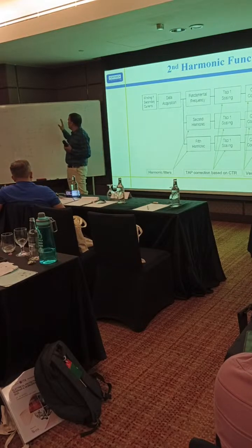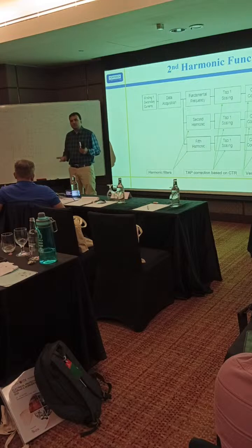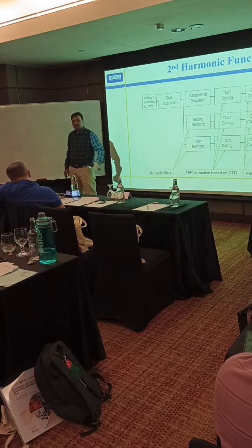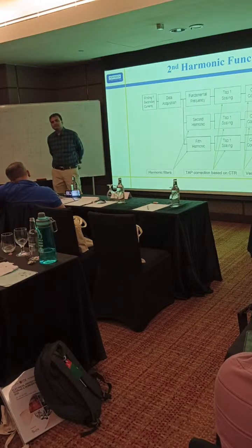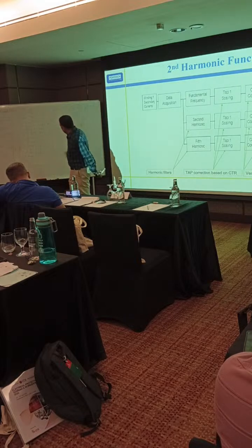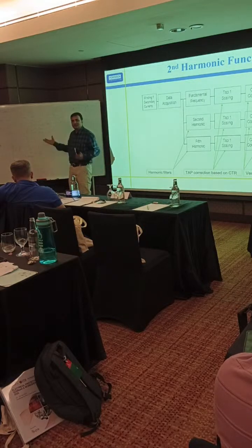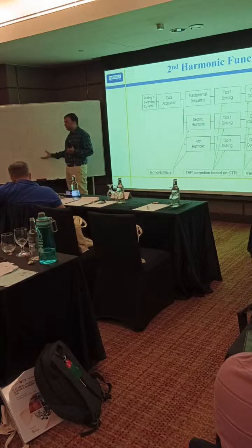You can inject fundamental current here, and that is also a method. Any way you can test. So when we inject fundamental in HV, the pickup value will be the same, 0.14, because there is no confusion. It is just the same winding. There is no confusion.